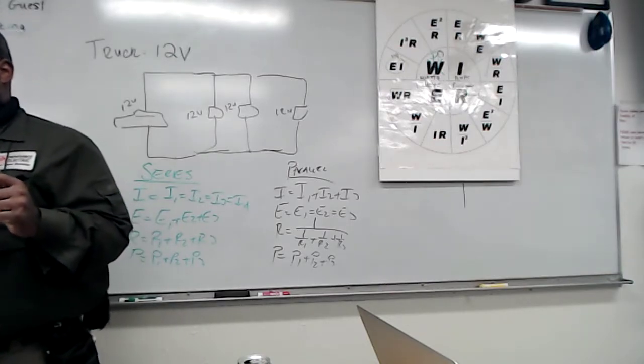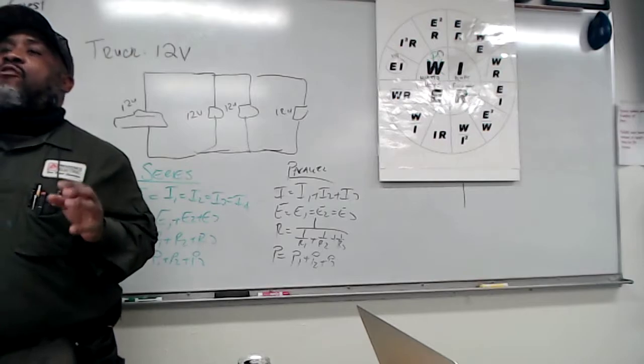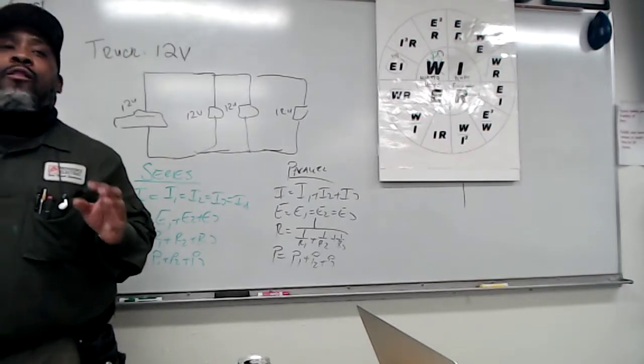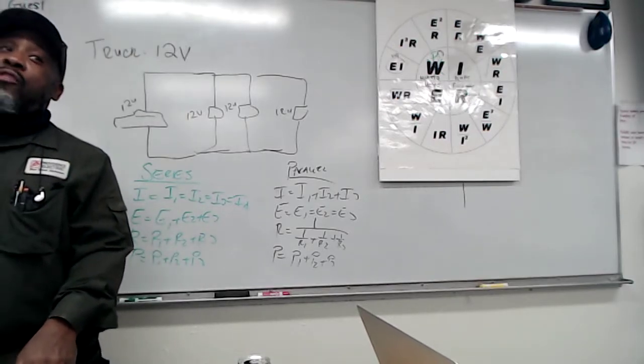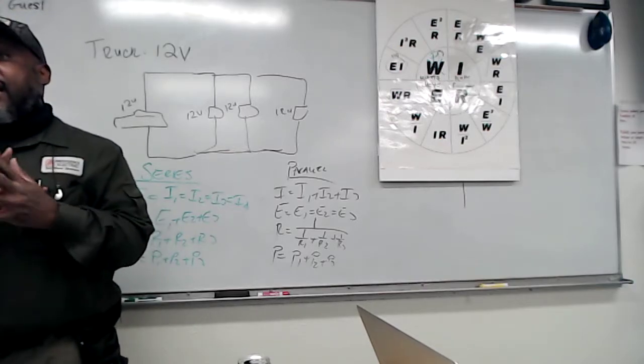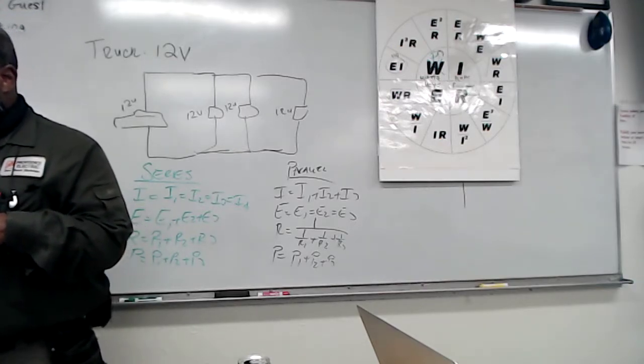You should highlight that. This table is only designed for a situation where there's not more than 3 conductors in a raceway. If it's more than 3 conductors in a raceway, we got to do some calculations. Y'all got that?